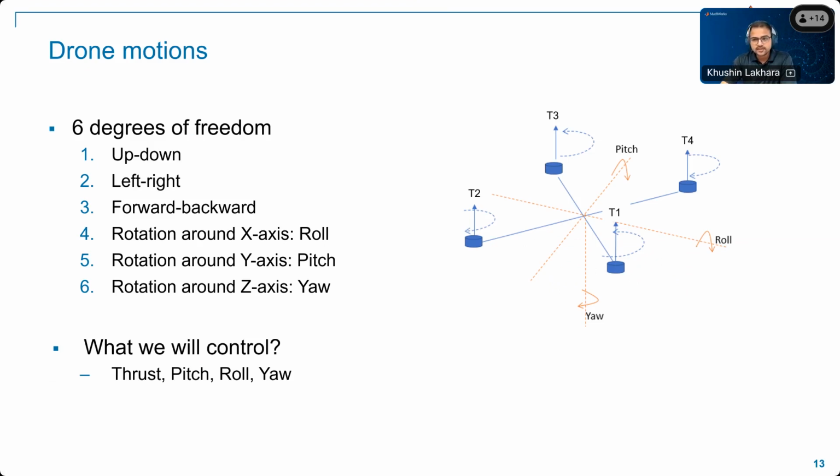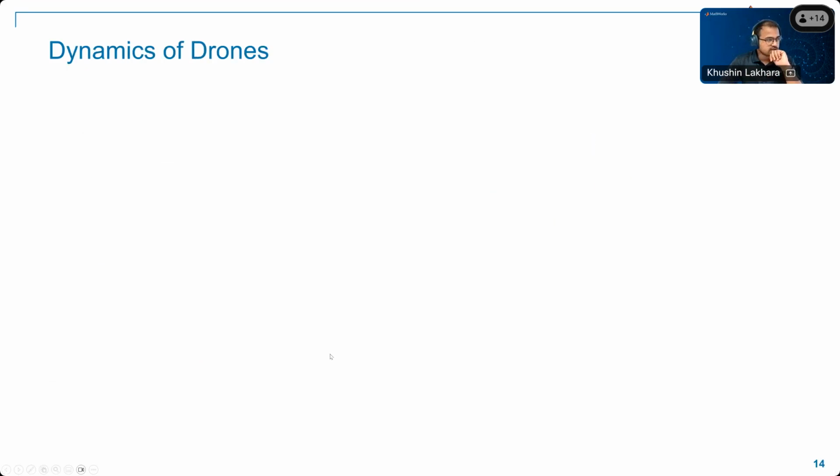So the idea is, if we only have thrust, pitch, roll, and yaw, our system is actually an under-actuated system, right? So 4 controllers are actually taking care of 6 motions. So how can we make that possible? That was a very good engineering problem when the drones, the UAVs, or especially the rotorcrafts, under-actuated system controls work started. So let's move on and see.